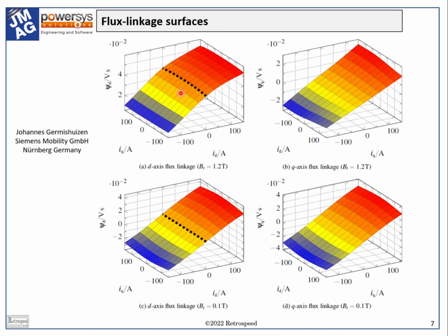The point here is that we have an example of a purely numerical process giving digital data that is partitioned to provide variable values for the terminal inductances LD and LQ and the open circuit flux linkage or EMF, without any reference to the classical partitioned components discussed in slide 4.